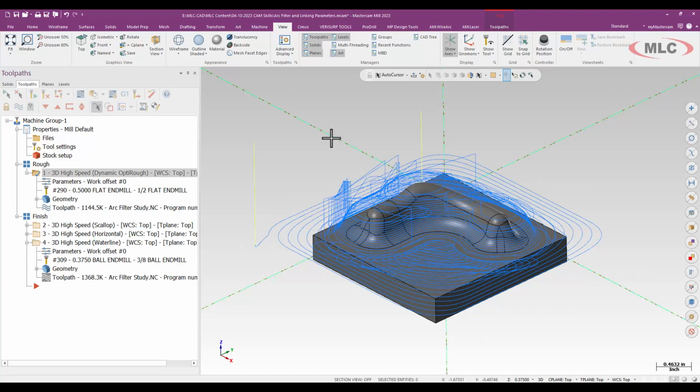So when I'm looking at the toolpath right now, and this is my op number 1, again, my OptiRough, I'm viewing this in your traditional sort of Mastercam color palette for toolpaths, which is basically 2 colors. I've got blue for feed motion, and you can see I'm moving around the part, repositioning using all feed rates, and yellow for rapid motion. And of course, I can see that at the very beginning and end of the operation where I've got a couple of just vertical moves to a clearance height and then back to it. Everything else is generally happening at a feed rate. I don't really get necessarily a lot of information beyond that.